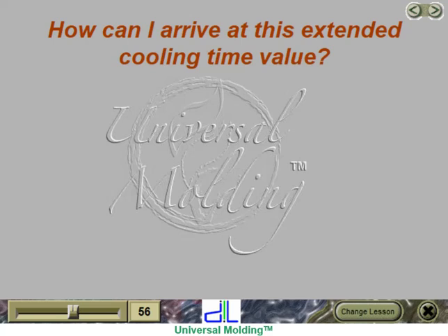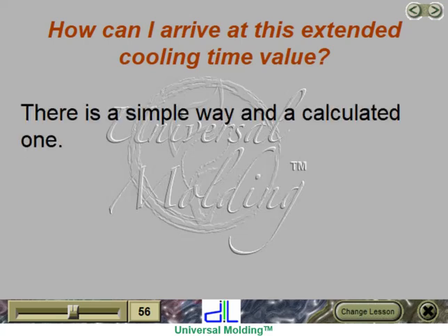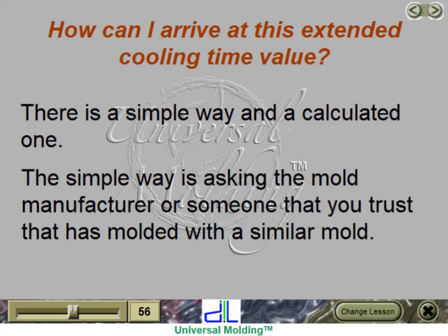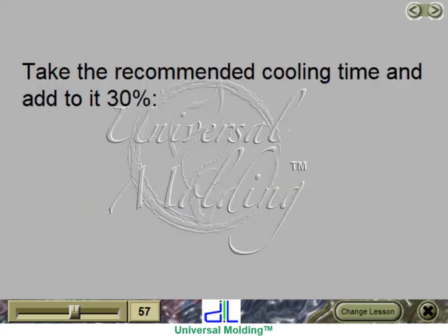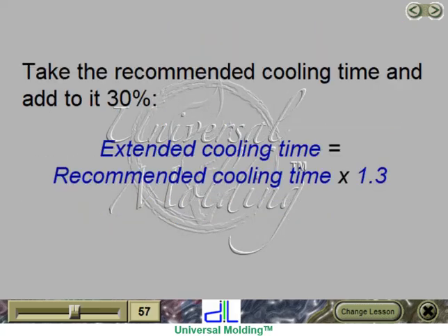How can I arrive at this extended cooling time value? There is a simple way and a calculated one. The simple way is asking the mold manufacturer or someone that you trust that has molded with a similar mold. Take the recommended cooling time and add to it 30%. Extended cooling time equals recommended cooling time times 1.3.